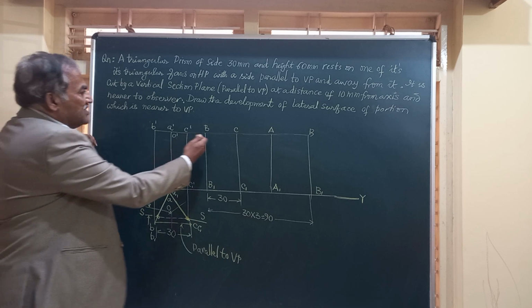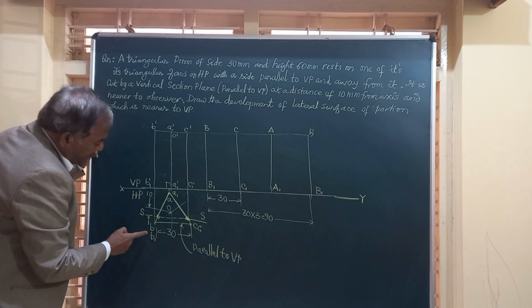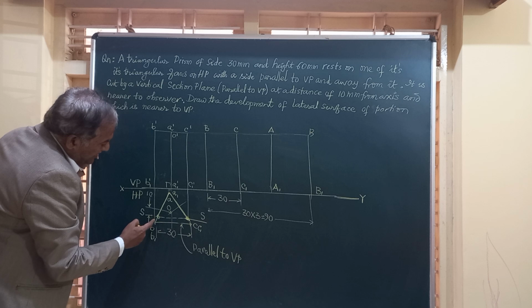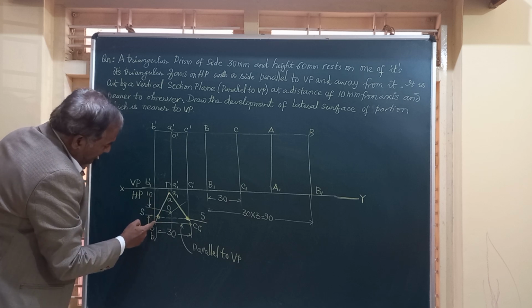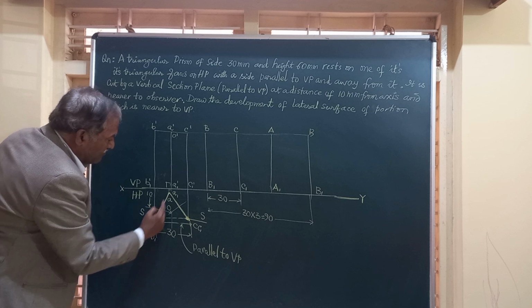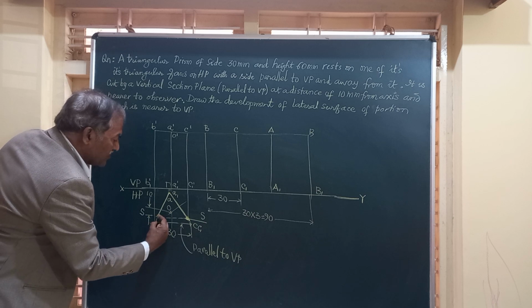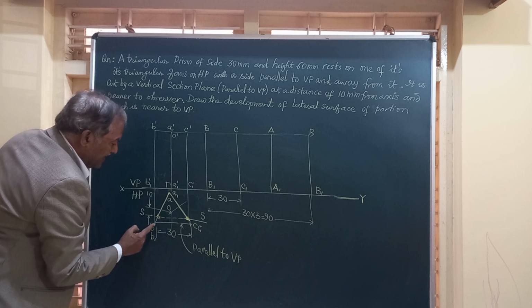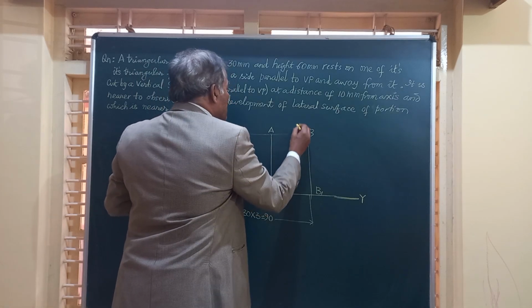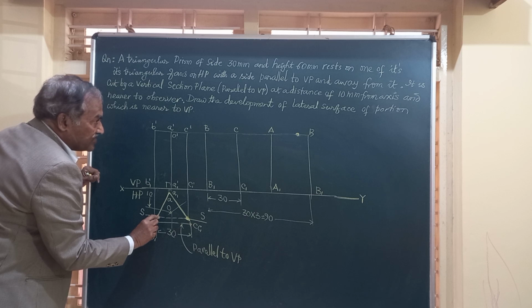Let us consider the upper surface and mark these. The section plane SS is cutting AB at the top at this point. Take the measurement, and on BA, mark a distance equal to this much, nearer to B. This distance is this gap along the edge.